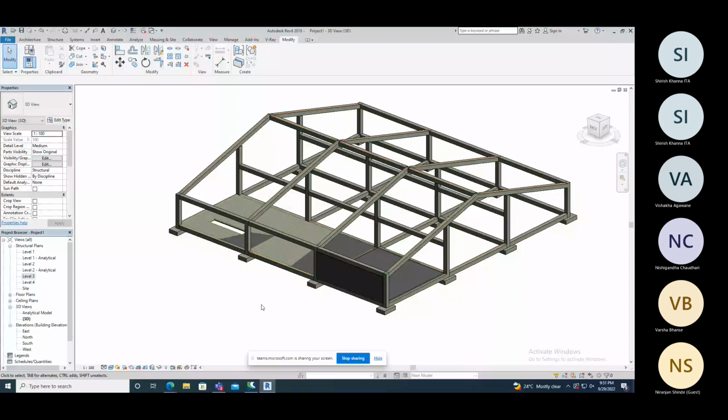So the reinforcement will be straight. It has to be adjusted in the top cover, the reinforcement cover. At the start of the slope, it may be less cover and more cover for reinforcement, and at the drain point, it will be minimum cover.